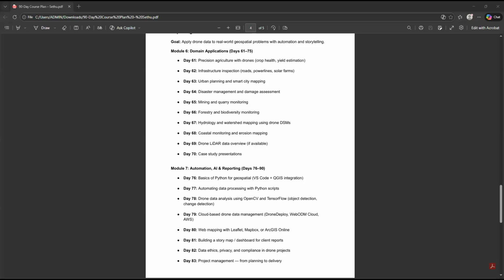If you have more payload, instead of going for a quadcopter, they'll go for a hexacopter or an octocopter. The more propellers you have, the more thrust it will build and the more lift it can generate so that it will take off. That is based on every application only, and drones are all customizable. There is nothing like a fixed or standard model. It is done based on what you want.